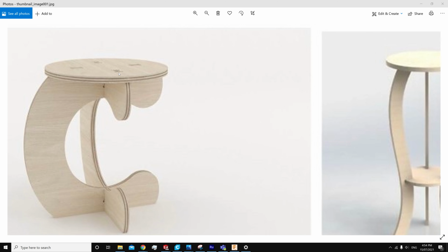Companies producing a large amount of cabinetry, doing cabinet fit outs or making furniture professionally might use a larger tool so that they can produce those in quantity faster. So for that, they may use an 8mm or 10mm tool. And a lot of cabinet companies will even use 12mm tools to cut their material. So that would obviously mean that a dog bone is necessary to deal with that. And you can see that here. There's a little hole which is visible.